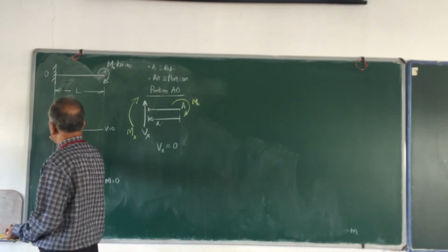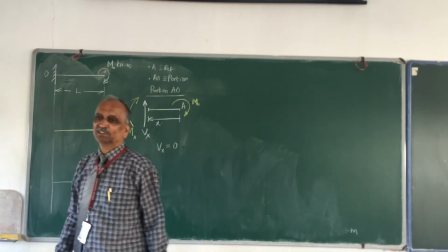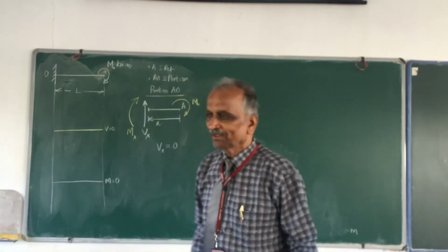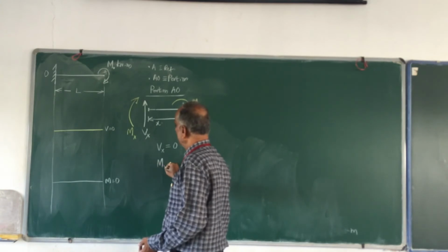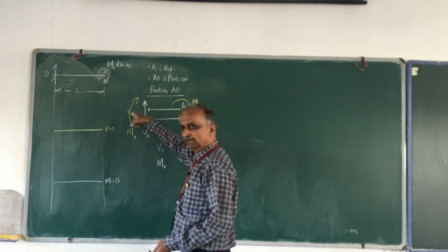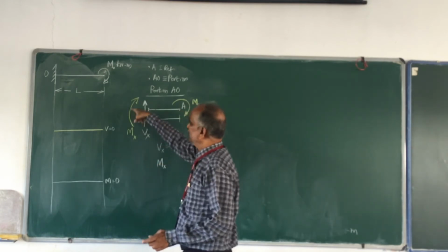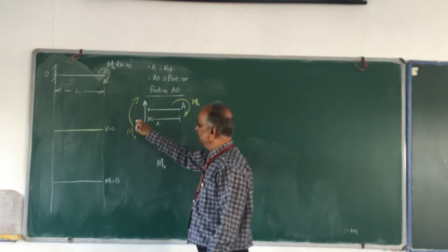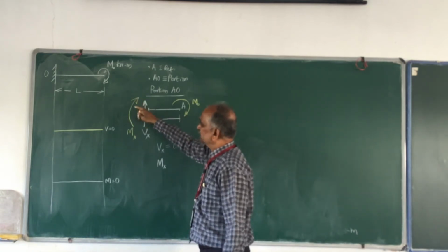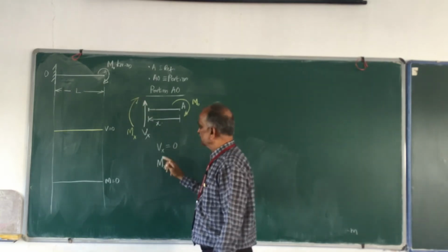Therefore, the shear force diagram is like this. This is your shear force diagram. Okay, so now let me go for what is called Mx. This is clockwise, and I have written clockwise as positive because I am writing this Mx as positive. It may be whatever the direction, and go back here, check what your positive direction of M is. So clockwise is positive.